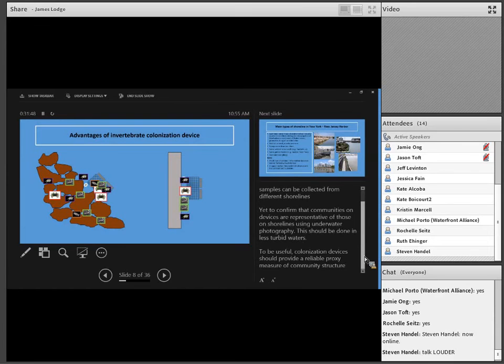We tried to sample these shorelines in clusters, if you like. So we would try to find some vertical seawall concrete shoreline that was close to riprap shoreline and sample them in tandem so that we could compare them, because we know that the water conditions across the harbour and across the harbour estuary will change quite substantially as you move from water body to water body. One thing to note from our initial survey of the shorelines, and that we'll come back to later, is that a lot of these so-called hardened shoreline doesn't actually extend far.